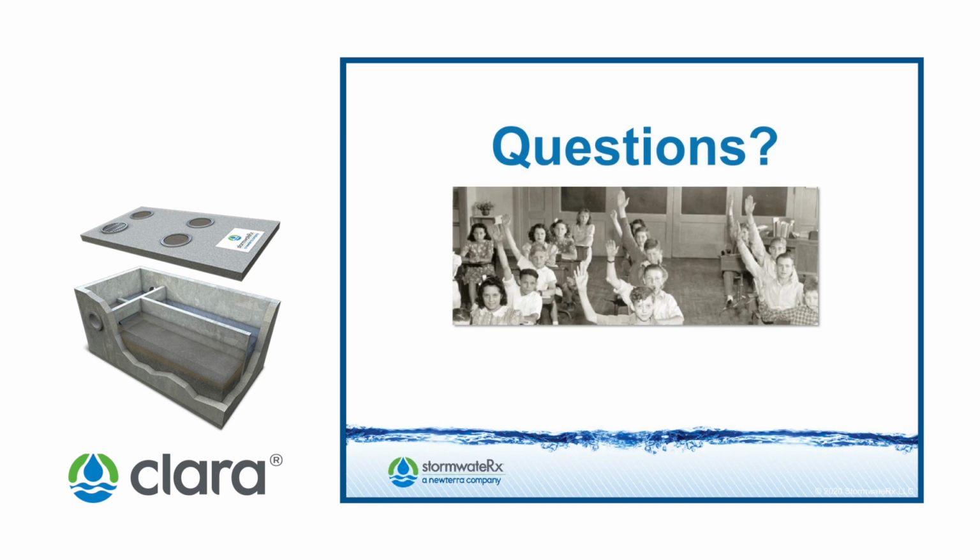Okay, well, not sure I understand, but maybe it's this. You might be wondering what available freeboard or excess capacity there is as the system starts to accumulate solids, so that it doesn't just go into bypass immediately once it starts filtering sediment out. So we do have a few extra inches of freeboard to account for that additional head loss as the media starts to collect solids, begins to occlude or plug, so that we have that available excess driving pressure to force water through even as the media is getting dirty. So it's a few inches. It's certainly more than is necessary when the media is clean.